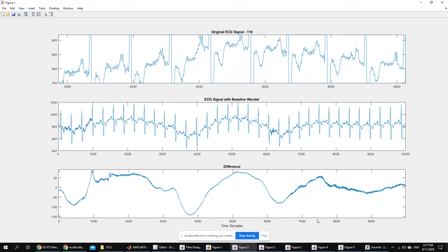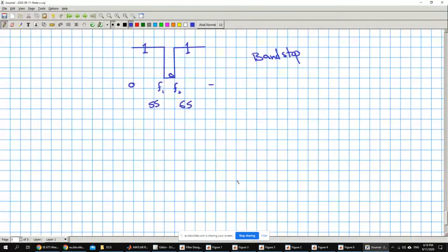It's much larger than the one we've measured for ECG. The period is much larger, which means that the frequency is much smaller. So the frequency here is almost 1/8, which is going to be like 0.125. So if I try to use a filter to separate a 0.1 hertz signal from another that is 1 hertz, which type of filter should I use if I want to preserve the 1 hertz signal? A high pass. Yes, it's exactly high pass.